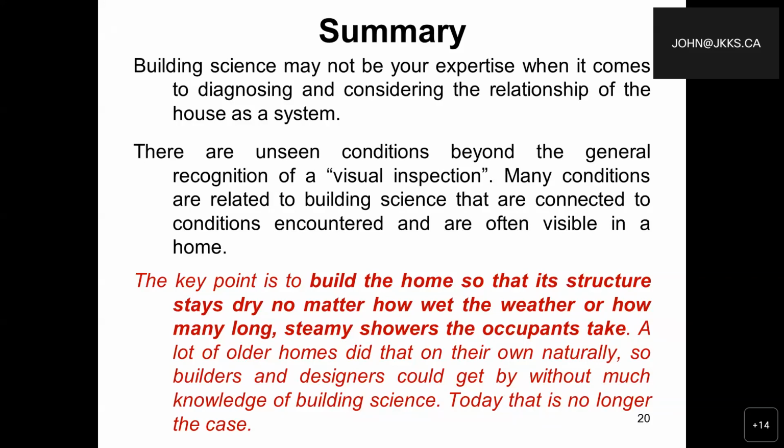We can see that, again, if we look at the visual physical evidence I've shown you in some of those photographs, water stains, surface warping, evidence of building component failure, those things are on their way to certainly causing problems within the house. These are serious hidden problems. Today, infrared thermal imaging, as I illustrated in that one photograph, has become essential for improving building diagnostics, as well as even more specialized testing. For example, when diagnosing air infiltration or exfiltration, problem areas can be isolated in preparation for repair work, even through something like a simple blower door test.